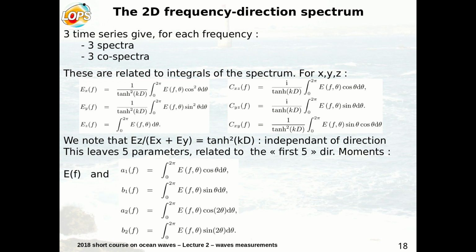There are ways to detect the peaks, and this is what's called the WDM method by Mark Donelan et al. So, wavelet directional method. With that, you can detect the peaks, but you cannot make a spectrum. You cannot say, well, that's a spread and like that. This method doesn't give you a directional spectrum, it gives you a directional distribution, which is not the same as a spectrum.